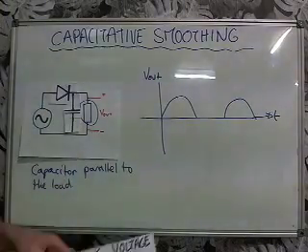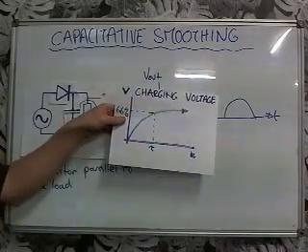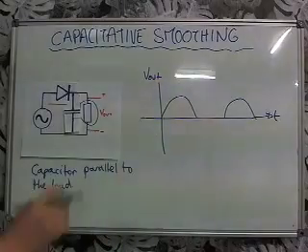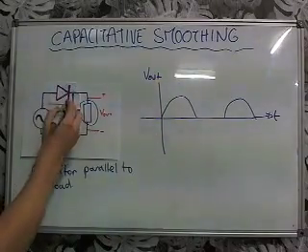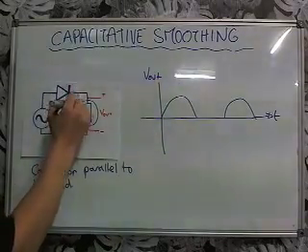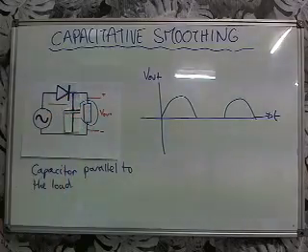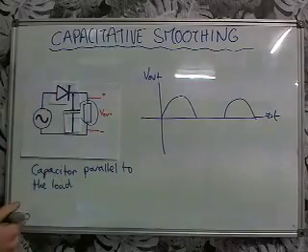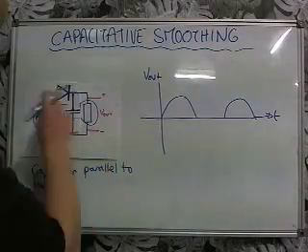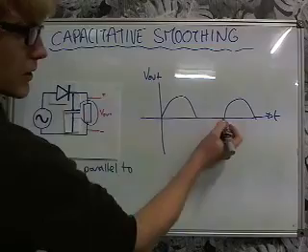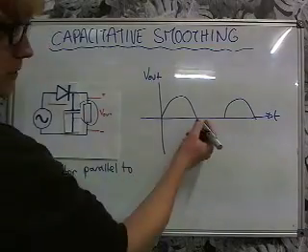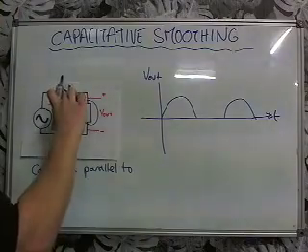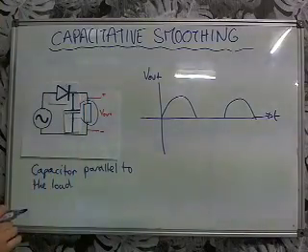Remember, we saw this graph of a charging capacitor. Okay, so the capacitor will charge when there's a positive voltage applied to it. That is, it will build up a collection of positive charge on this plate here and negative charge on this plate here. Okay, it's storing that charge in the plates. But then, when this applied voltage disappears, in these parts of the graph here, there's not going to be that electromotive force pushing that charge onto this plate anymore.